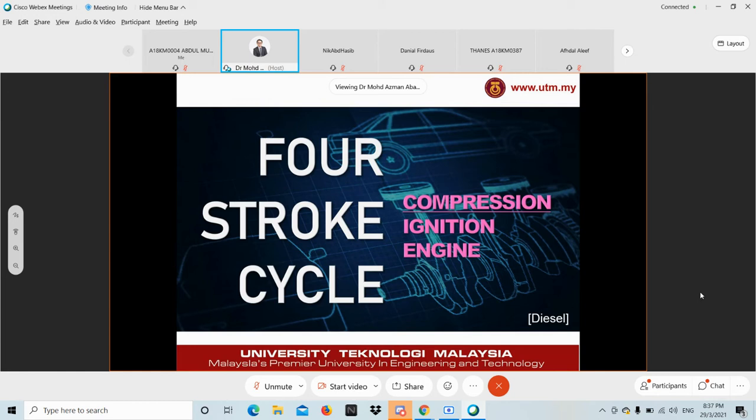So I will definitely explain that in the later chapters. We will cover the ignition timing, the combustion punya chapter on that. But definitely knocking ni can be classified as severe or not severe. Sometimes it's very severe. When it's severe, the engine management system is clever enough to retard your ignition timing.